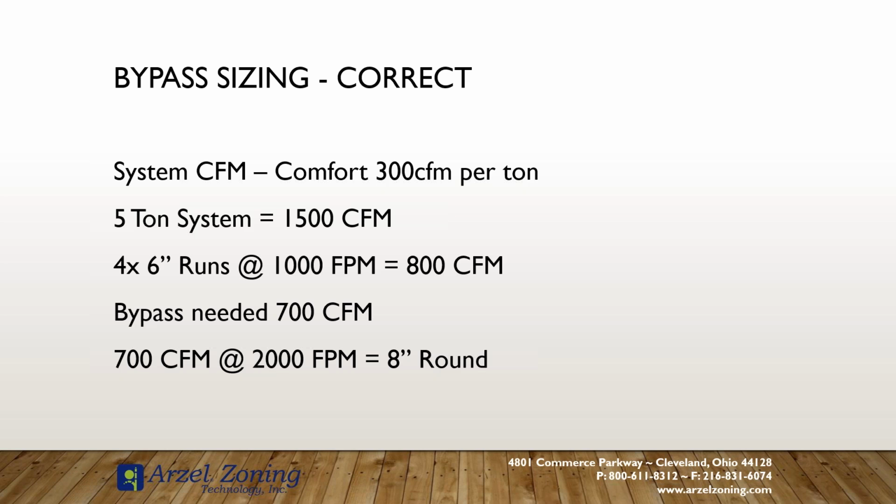So two-stage equipment plays a really important role in maximizing comfort, performance, and reducing the need for a bypass. And the Heat Pump Pro is the best zoning control on the market because of the way it uses its own weighting. It's a true customization rather than just a minimum calling zone. So if I'm sizing my bypass now and I have a two-stage furnace, I'm going to size it based on low stage capacity. And what I would find in this application is that a bypass isn't necessary.